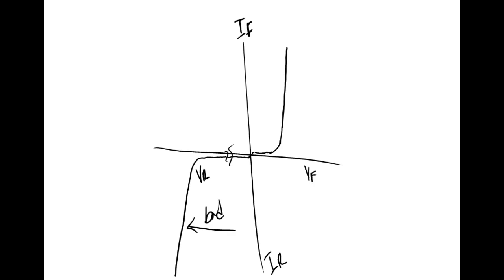Now, the diode that we're going to do is the little small signal diode, because it has a very low VF. It's got a VR of around 80 volts. So we're going to deliberately break it over, but we're going to put a 10 meg ohm resistor in series. So even when it breaks over, it's not going to hurt it, because that 10 meg ohm is going to really limit the current, right? You understand this happening. But we're not going to do that section of the lab as units because it takes about 80, 90 volts to break this thing over, and that's pretty dangerous. So we'll do this as a class.